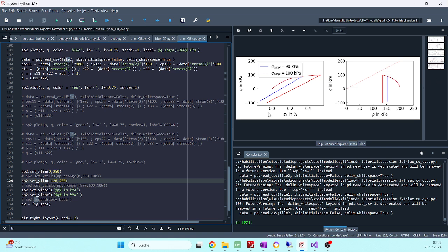Now we see here that we are performing, first, we are loading the sample with 90 kilopascal, then we are unloading it with minus 180 kilopascal, so to come to the same stress here in extension. And then again, we are doing the same. This is in effective stress space, and in q versus epsilon 1 space, that would be loading until 90 kilopascal, then unloading, reloading, unloading, reloading.